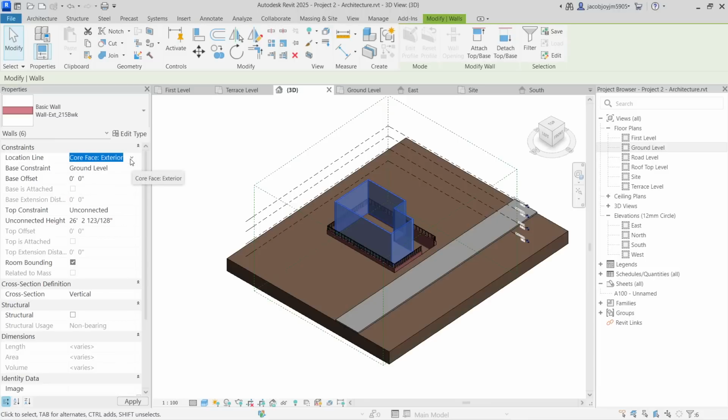Okay, so the architecture model is basically used for visualization. The construction model will be different. So please understand the difference. Okay, I will show you an example. For visualization, we draw the floor inside the wall. If it's for construction, as in reality, it has to come till the edge of the wall, right? That's the only difference. I'm showing you this because you need to understand the purpose of the model.